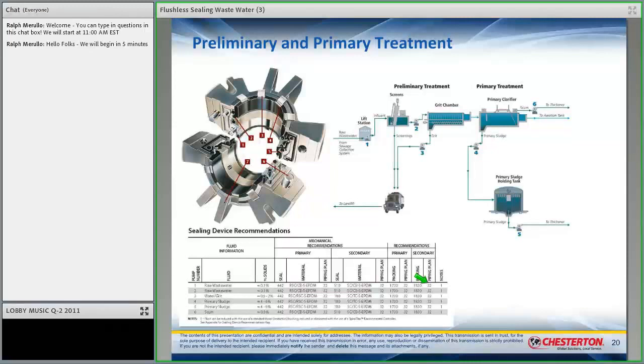So what we've already described are: use a restriction bushing, that's one way to do it; use a spiral track device, that's another way to reduce flush with packing. You can completely eliminate flush with a dual seal, right? So having fluid from a tank, pressurizing it, that will completely eliminate flush, but it's more expensive. So now the plot thickens, because then the question is, well, can we have a solution that works without a flush that does not require a dual seal? What's the ROI? Give us the cheapest thing that's going to work, right? Exactly. So that's where we live. That's where things get interesting.